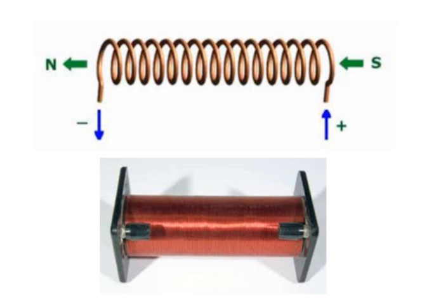So therefore, on this one here, I'm going to use my right hand. And you're probably going to see this one better. As you hold your right hand up, can you see how my fingers are curling over the top like this? And therefore, my thumb is pointing to the north, right? I'm starting here, and I'm saying my hand is wrapping over the top. That's the way we wrapped it. I could have wrapped underneath, but this was an over sort of wrap around. And so that's why I'm using my right hand on this one, because they indicated that the electrons were going from positive to negative, which is actually conventional current, not electron flow.